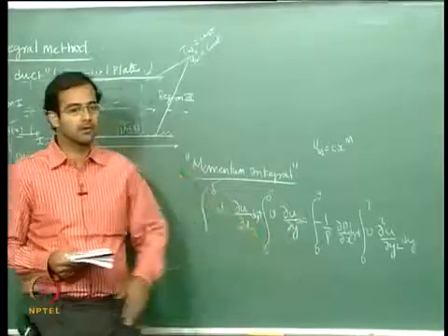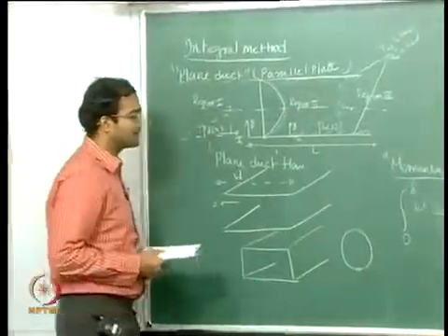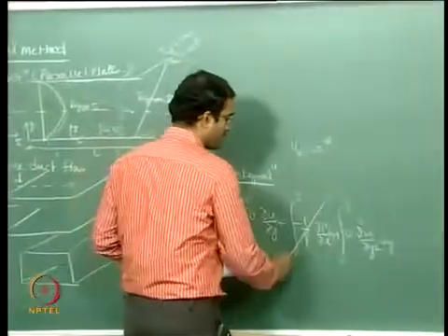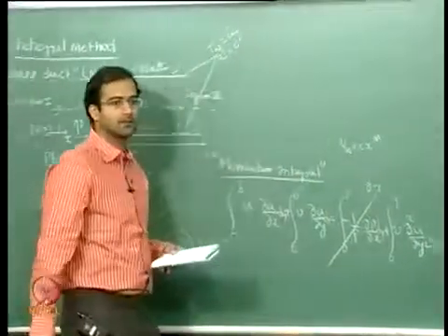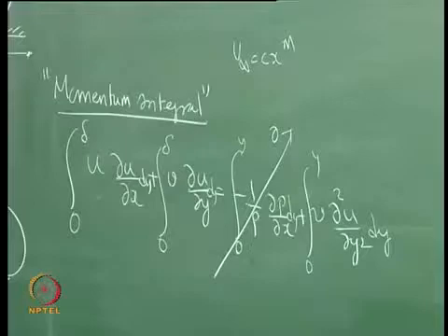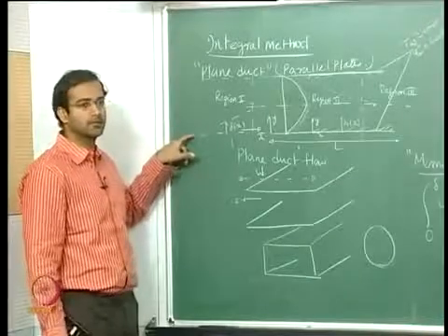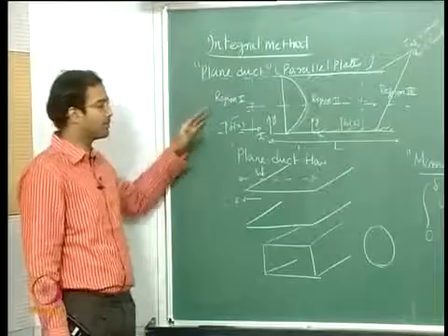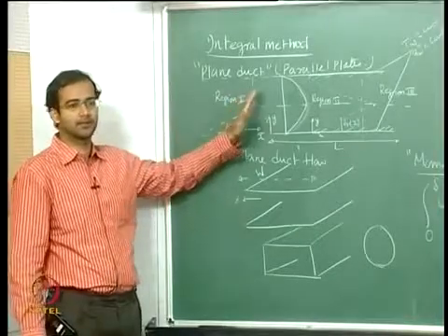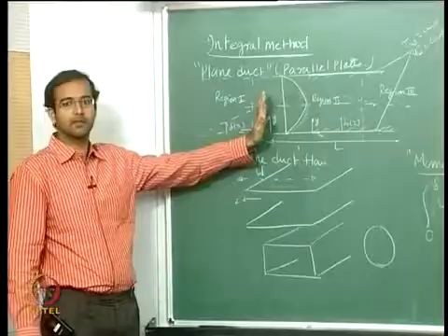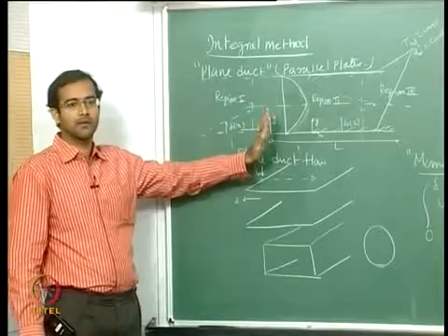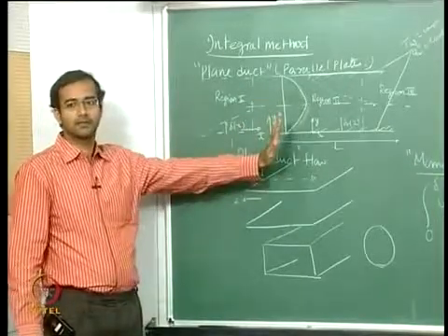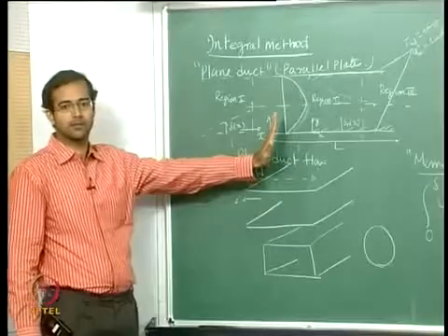So therefore one level of approximation would be to directly neglect this, because the pressure gradient terms will not be so much when you look at the initial part of the boundary layer growth. They will become more and more dominant when the two boundary layers start merging, and once it is fully merged, then only the pressure gradient term will balance the viscous terms. The initial terms will not be there.